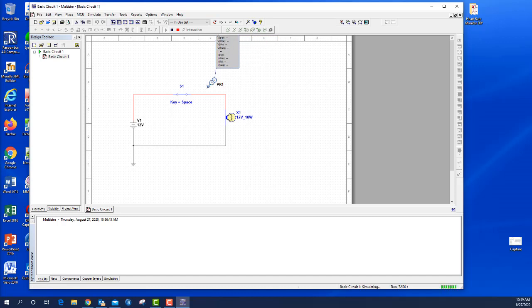And we're going to have to place the probe on a wire. When you have the probe in an acceptable location, the info box will turn yellow. See that? It's gray otherwise. So let's put it right here, coming into the bulb. And so then you can click on this box and you can move this around if you want to, because sometimes you can use more than one probe. For example, I can bring another probe over here before the switch, like that.